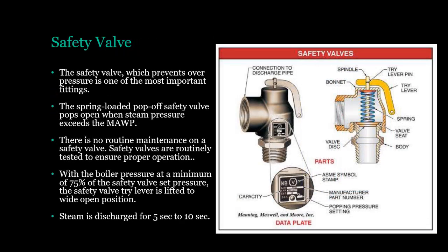The safety valve, which prevents overpressure, is one of the most important fittings. The spring-loaded pop-off safety valve pops open when steam pressure exceeds the MAWP. There is no routine maintenance on a safety valve. Safety valves are routinely tested to ensure proper operation.